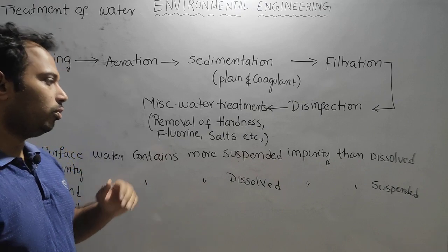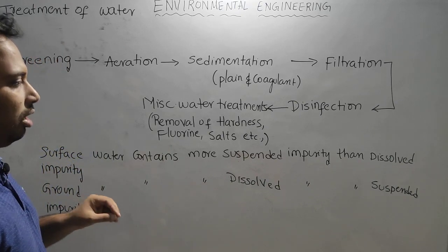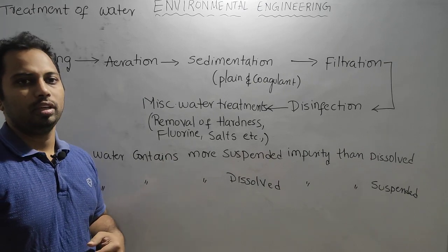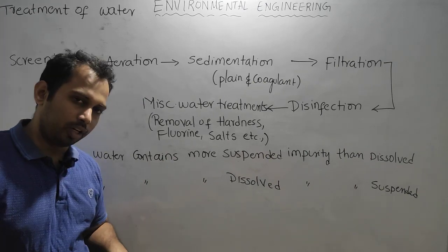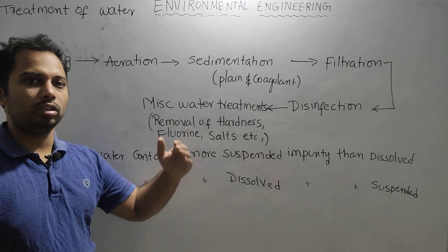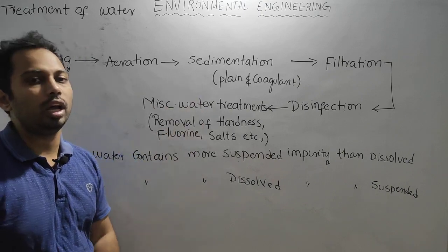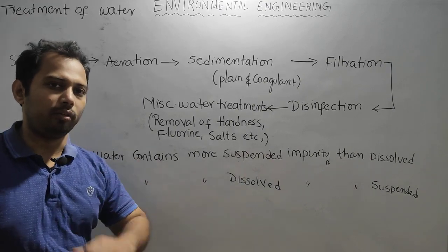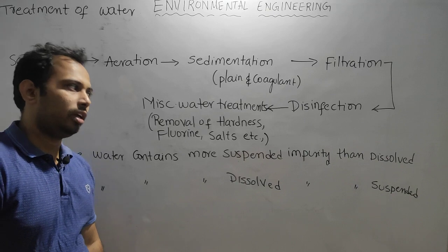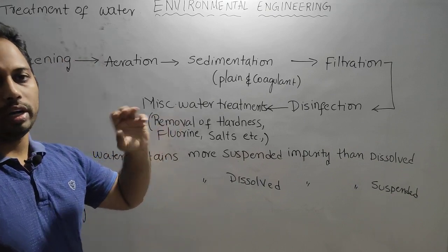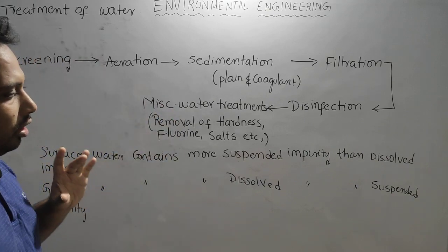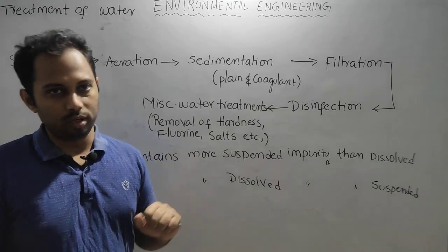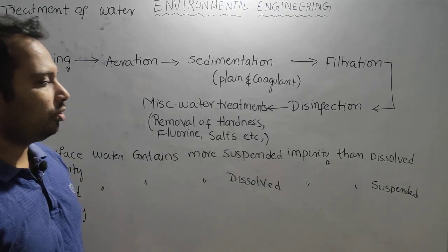The suspended impurities are removed by that filter media, but the dissolved impurities remain with the water and reach the groundwater. Groundwater does not have any interaction with the environment as surface water does, because it is completely covered with earth. So the dissolved gases and dissolved ions will remain in the groundwater.